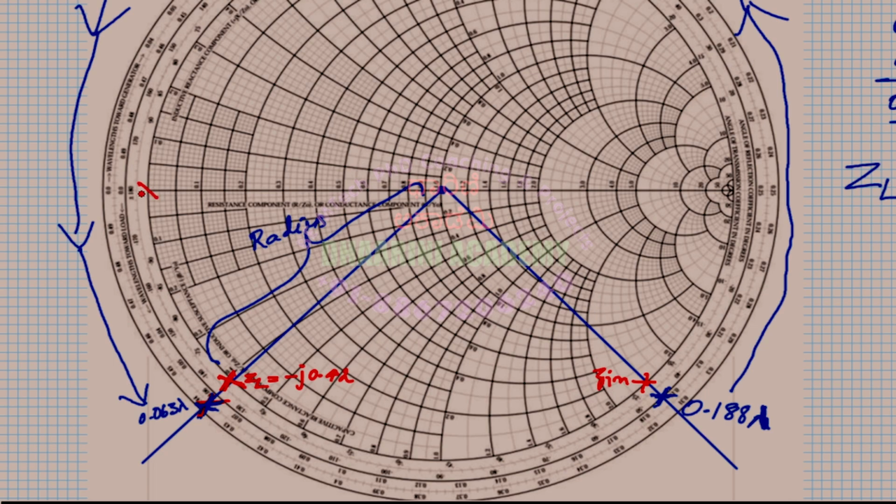So this is the point, that is Z minimum, because when I use this as a radius, I'm going to follow this line as my path and reach there. So that is the Z minimum. Since this is the point, it is actually the short circuit, correct? The point corresponds to Z min, so Z min is equal to 0 now. It's a short circuit.